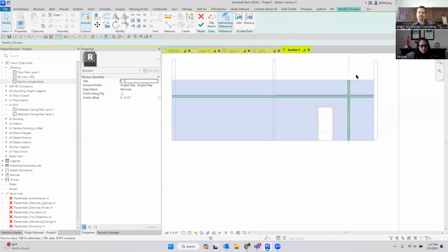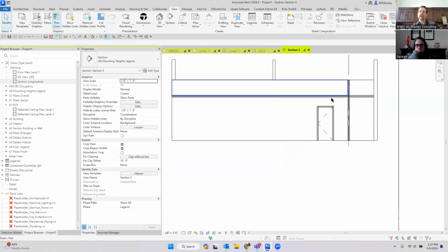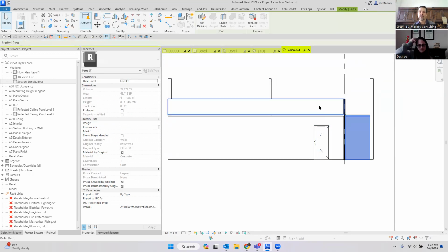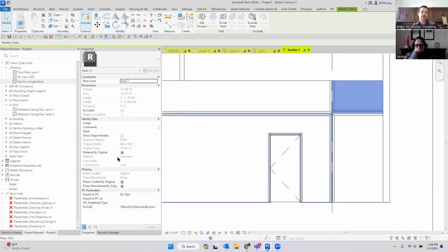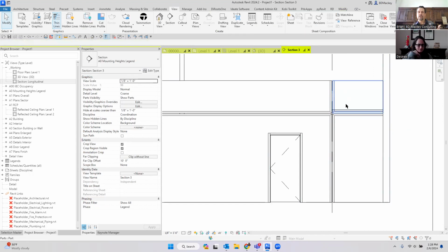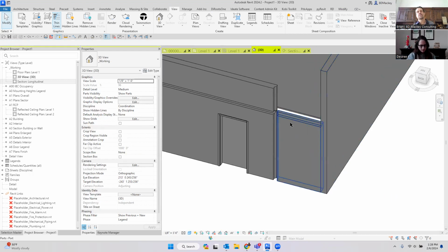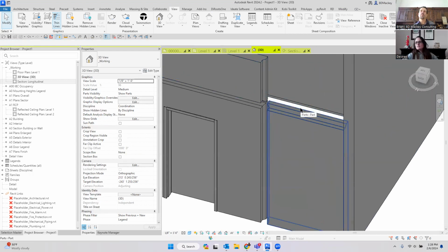And the nice part, I think I grabbed the overall part, but you can start doing the individual components and start adding additional parts. And you'll see here's an advantage. Once I divided that part, now I have 4 parts from that one wall. So again, now I could make this one bigger, this one shallower, whatever you need to do, you can start getting into it. Or even you can come down here and just say, hey, I want to exclude this part. Where is the exclude button? It's up here. And now I've excluded that part. So theoretically, it thinks my building now has a notch out of it. Right. Still technically in the main wall. I didn't edit the profile of the wall, but we can have this in here.